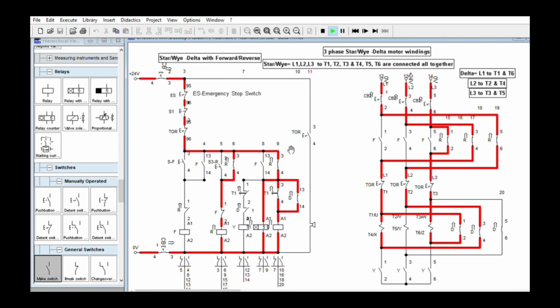Sometimes it is not a multi-contact contactor. You need to purchase an additional extension contact or auxiliary contact, so a bit expensive. This is fine. No need to double interlock.